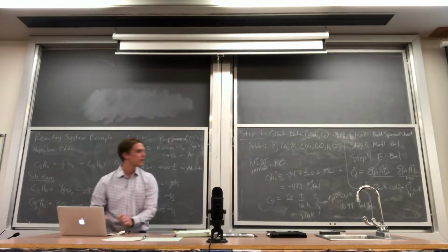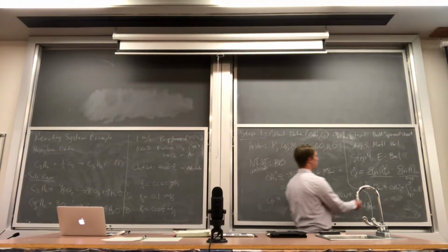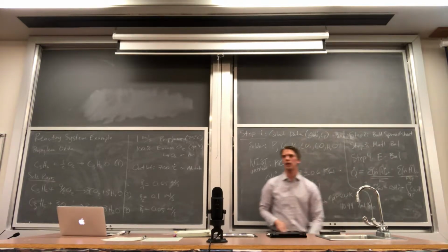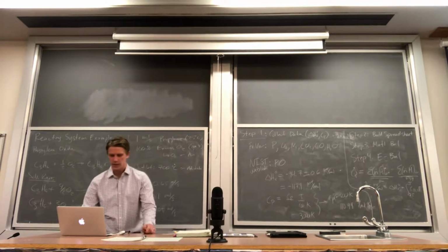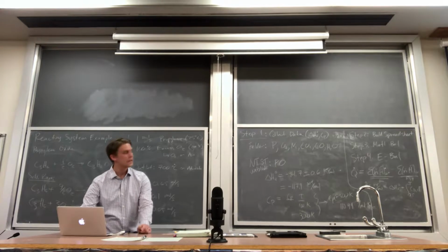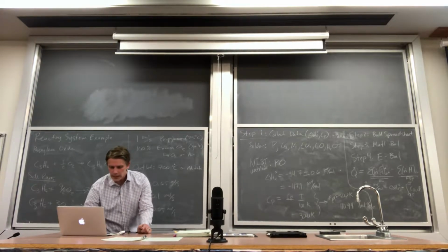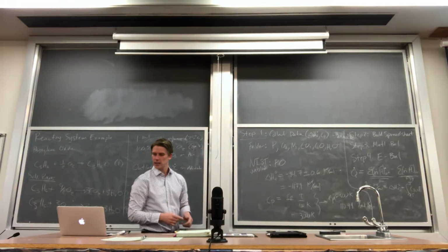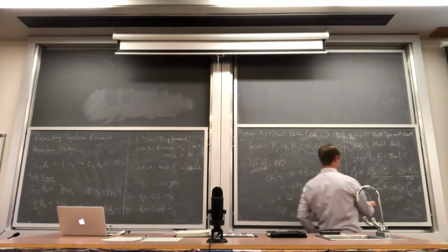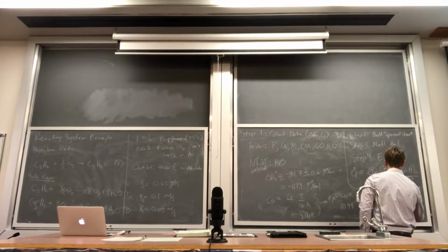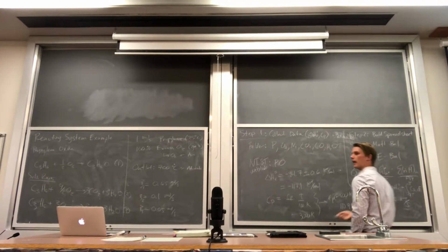So now I want to solve for Q. All I need to do is take all of the enthalpy out minus all of the enthalpy in, and I have balanced my process. And that's exactly what I've done here. I have taken the blue, which is the out, minus the red, which is the in, and my Q is 98 kilojoules per second for this process here. Q dot is equal to 98 kilojoules per second.